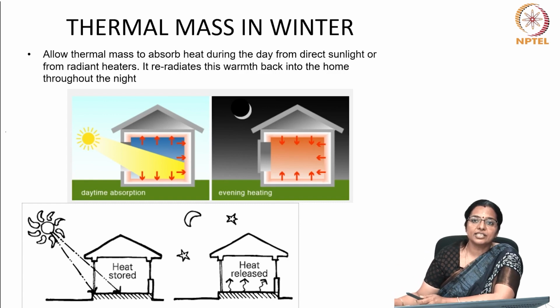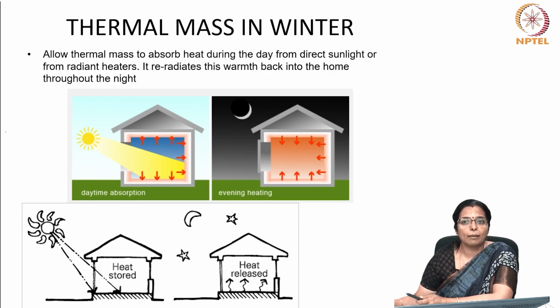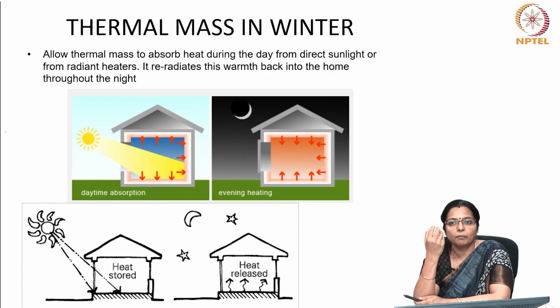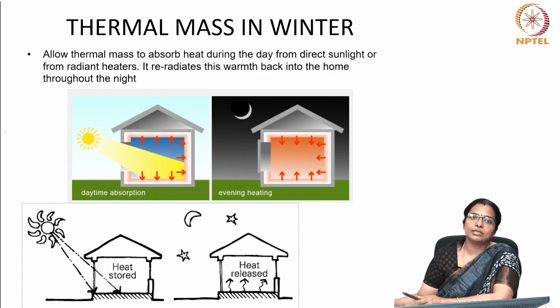Because thermal mass distinguishes itself as a tool for dampening of temperature amplitudes, it works best when excessive heat builds up and requires absorption and much later disposal. For example, where the excessive heat generated by solar gain is absorbed by the building fabric during daylight hours, or where a particular environment has excess heat generated by the people who stay inside, absorbed and then emitted into a cooler nighttime space.